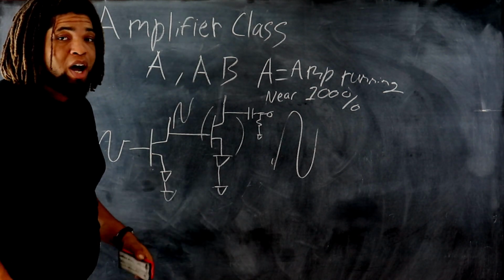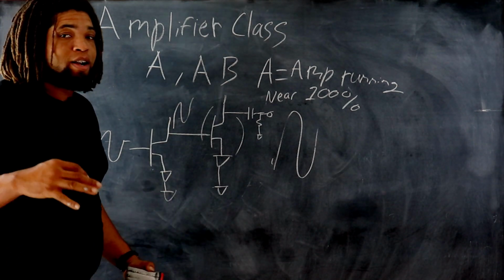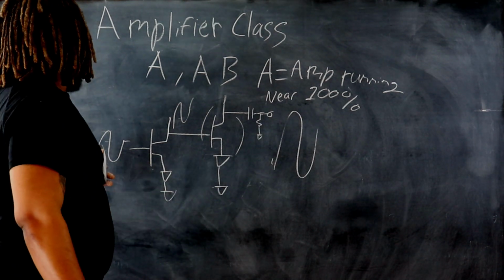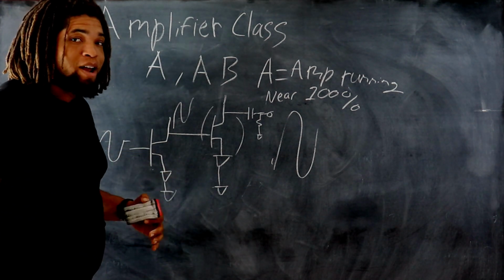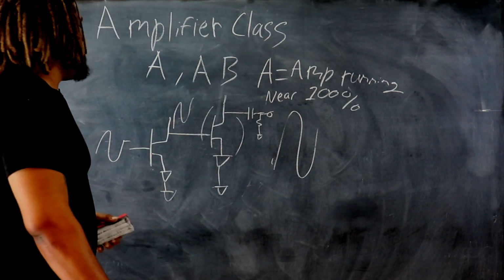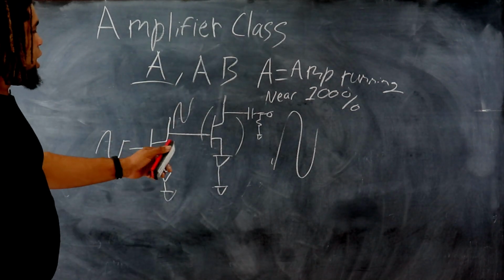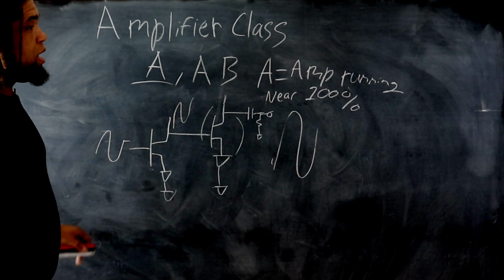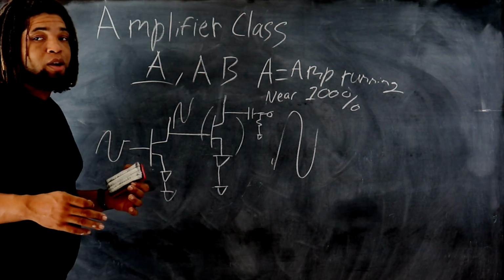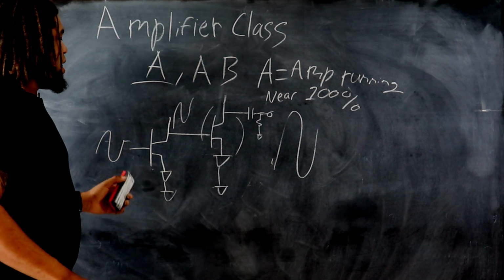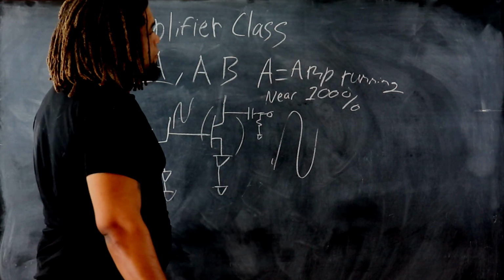And that's what we're always looking for in audio, is trying to reproduce the signal at a higher voltage, higher current, higher wattage, but wanting to preserve the signal's characteristics. So we don't want to modify it very much at all, right? So doing a Class A helps us with linearity. It helps us preserve that input signal, which is the recording that comes from an MP3 or a CD, and preserves that signal as cleanly as possible throughout the amplification process.